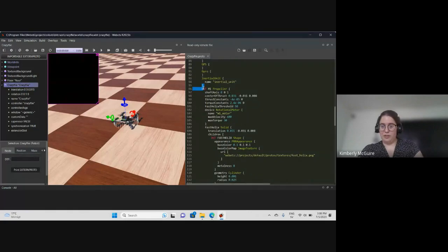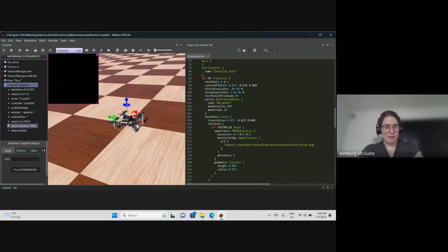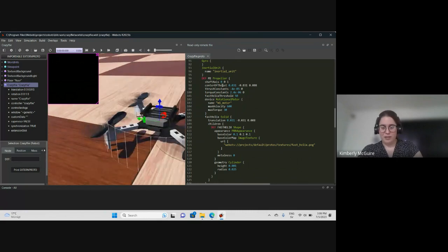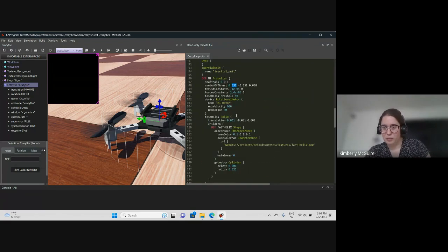These are the propellers that I mentioned, which are maybe the most important part of the Crazyflie. If you look in there, I'm not able to select them because I don't have the full controller there. But you have the center of thrust, which is pretty much the location of the motor. What are the thrust factors? Let me just double check. Thrust constant or torque constant.